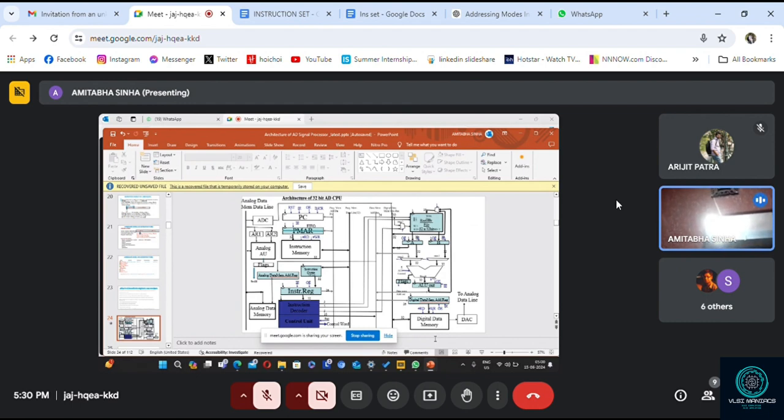Now, if you want to multiply two numbers, A and B, how do we do it? Log of A into B equals log A plus log B. So you take log A with one operational amplifier, a logarithmic amplifier, and the output will be log A. Another operational amplifier, it will be log B. Then you add them by using a third operational amplifier, and the output will be log AB.